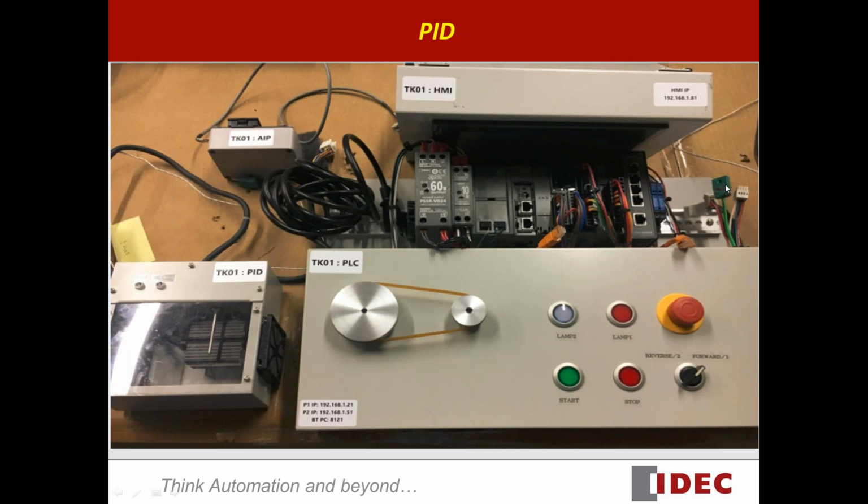That's going to be my PID PV, or process variable. Take it into the PID box, to the PLC. And then my PID output, guys, is going to the heater. So I'm going to set a desired temperature inside that box, and I'm going to measure the temperature and change the temperature inside that room. Let's say you're, I don't know, breeding or raising shrimp in that box or something. You want to maintain the perfect temperature. Think about it that way, because that's the best I can demonstrate.